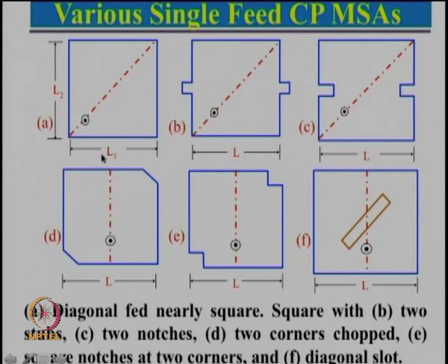As we change the frequency from F1 to F2, the dominant horizontal polarization changes to vertical polarization, but in between there is circular polarization. This configuration gives larger bandwidth from an impedance matching point of view, but a very small axial ratio bandwidth.